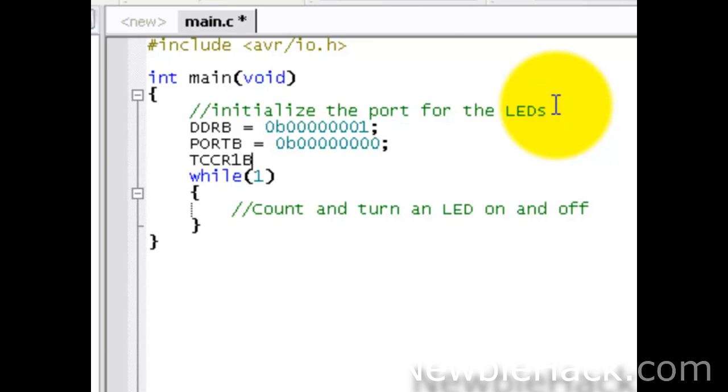And that's the particular register we're going to be using for turning timer counter 1 on and giving it a pre-scaling of 1, which means it's going to tick in rhythm with the internal clock. So let's just use the shift and the OR-equal bitwise operation: 1 shifted to turn on CS10, as we saw in the data sheet.